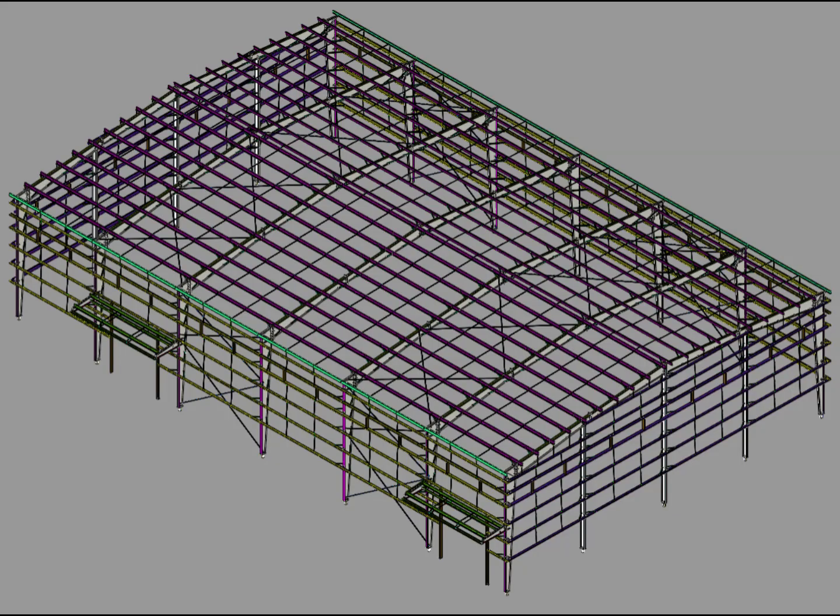A PEB roof normally contains a series of purlins arranged along the roof. These purlins support the roof system and transfer the applicable loads toward the primary structural frame. The sag rod is provided as part of this secondary framing system to provide restraint and help maintain the required position and stability of the purlins, according to the project design. This is why the sag rod appears as a much smaller member compared with the main roof framing members. And this is also why identifying it correctly in a PEB drawing is important.